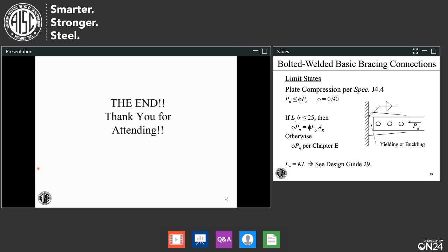Well, there was an AISC journal paper from a few years ago. Don't remember who wrote it, but it was probably about 2000 to 2005, and there were a few different examples in there. And I do remember one was similar to this, and in there they were using 1.2. And then there's also where the 0.5 came from for the gusset that's connected to the column and the beam at the corner connection. So they have 1.2 for some of these. For some connections that look about like these.